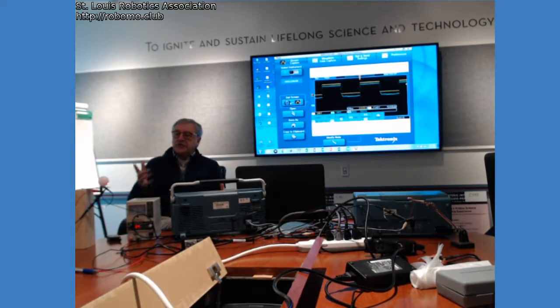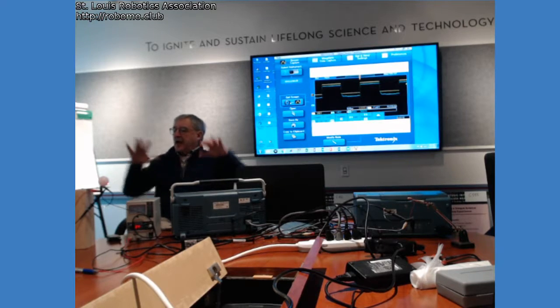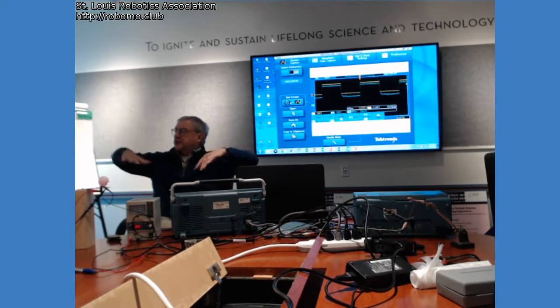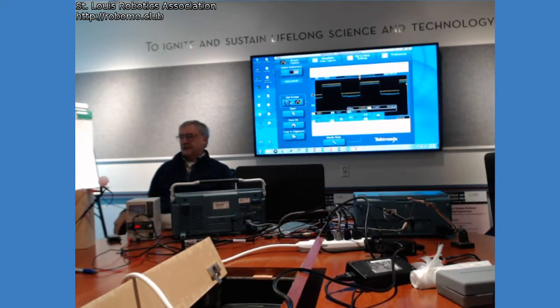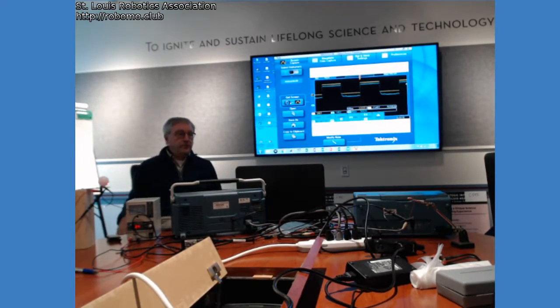That's one of the advantages. And the reason I didn't use a phototransistor here was that I don't need that extra gain. That's already too much. Plus, what I found was that this had the widest field of view of any device, between all the photodiodes and all the phototransistors that are in DigiKey sells. So I said, okay, fine. It wasn't anything more complicated than that. So, yeah, I'm a little lost.